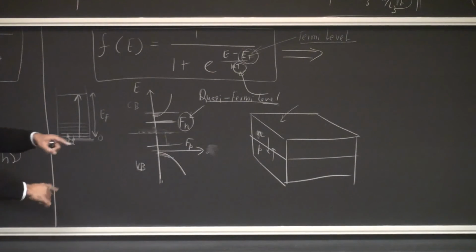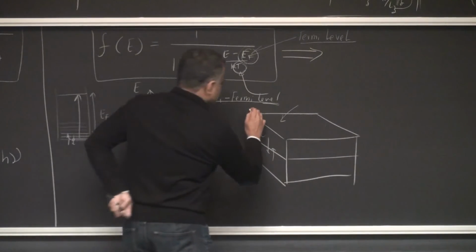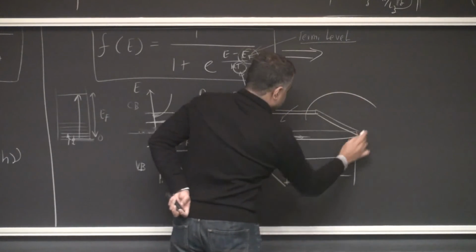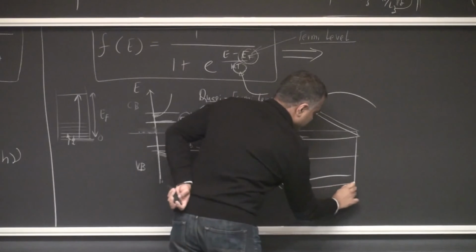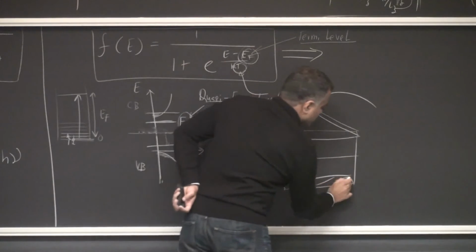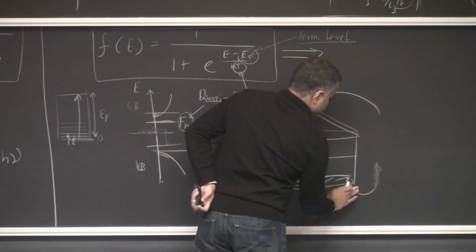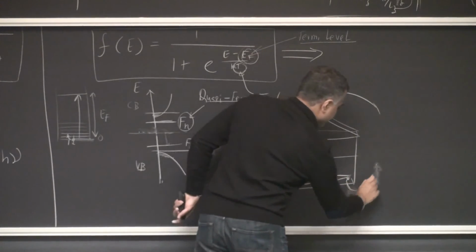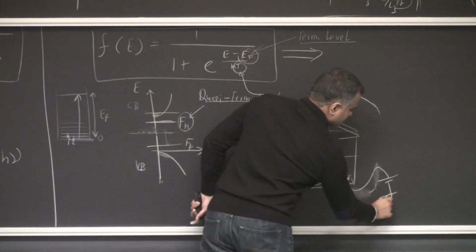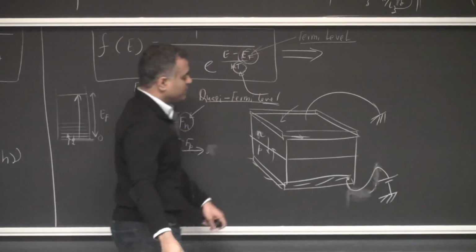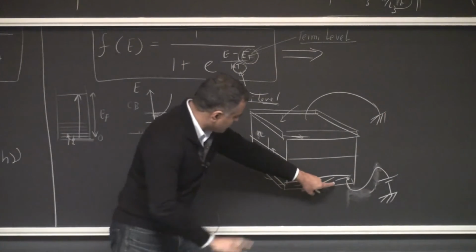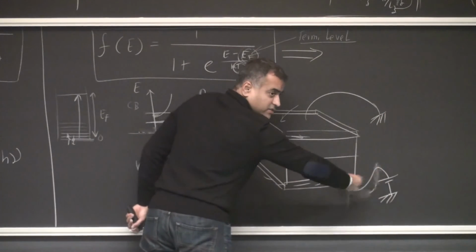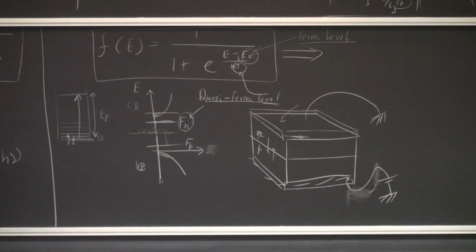And how am I really physically changing these Fermi levels? What I do here is I physically make a metal contact, and I connect a battery. Now that's what is actually tweaking these things. So let's sketch this as a p-n junction. Let's say we ground one end and we connect a 1 volt or a 2 volt battery to the P side. I think you know that it will try to flow a current, right? A battery wants to push a current through it, will inject carriers and all that.